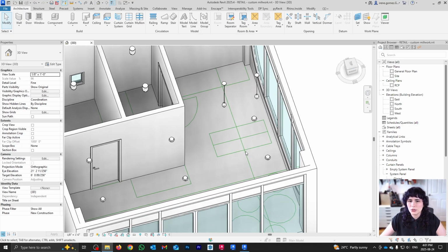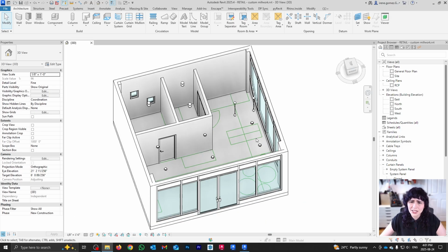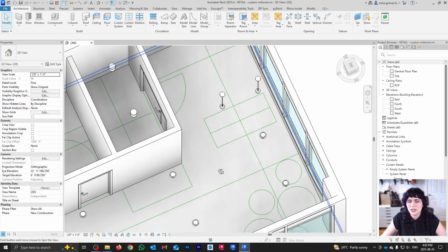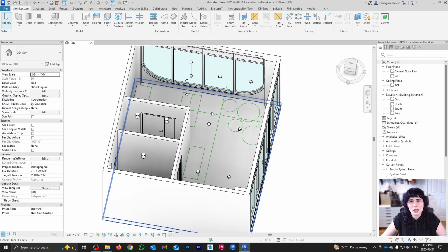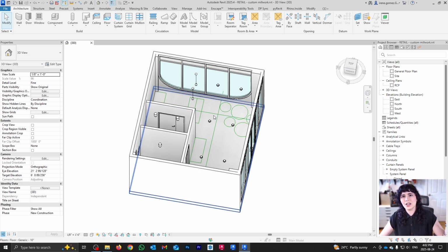I'm going to start easy with this pay area here. And what I like to do for setup is start by creating a section box that will make it easier for me to move around the model if I need to. Because let's say that I need to look at a detail here, but this wall keeps on getting in my way. Once you are inside the model in place component, you can't interact with your section box or with the building in general, which can make it a little bit annoying. So what I like to do is set this up before I start modeling.